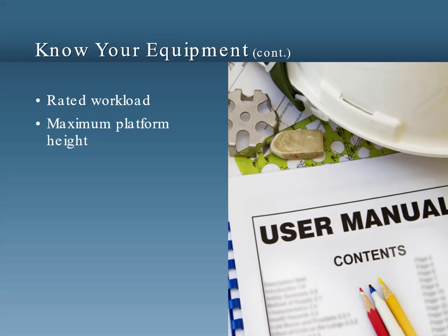Equipment can have different maximum heights depending on whether outrigger devices or stabilizers are used. Always check for maximum height. Even if you've used other equipment, the equipment you're using now could be different. Never exceed platform heights.